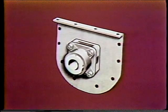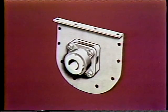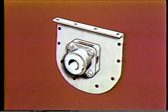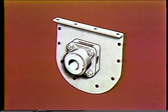The trough ends are either steel or cast iron and have a bearing mounted in the center. These bearings may be either ball, roller, or sleeve, depending upon the material to be handled. They must be able to take the thrust which the screw transmits to the trough ends. That is, unless the bearings in the reducer absorb the thrust.